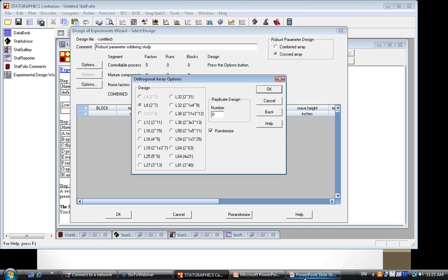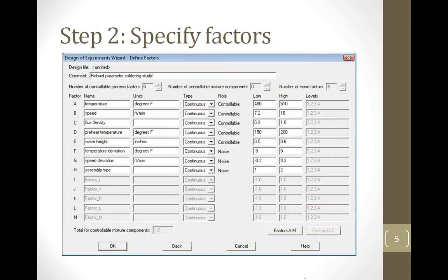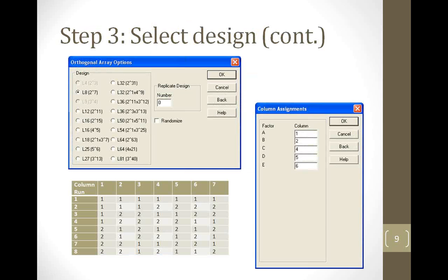Now, by the way, if I go back to my PowerPoint presentation, I did make a copy on the slide here of what Taguchi's L8 design looks like. In the bottom left here, you can see the 8 runs the way Taguchi lays them out. And rather than using, for example, -1s and +1s that you might be used to seeing in factorial designs, for the 2 levels of the factors, Taguchi just called them level 1 and level 2.